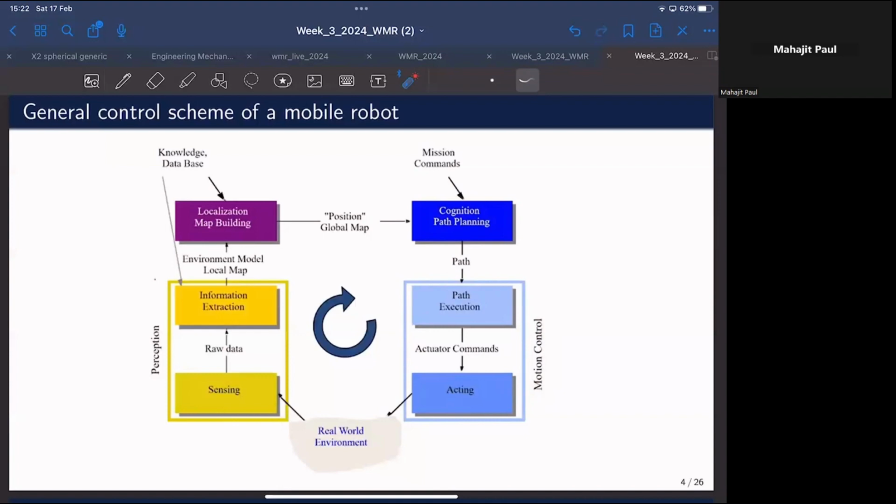By comparing all the data internally from the robot as well as what it is receiving externally, it will make sure that the robot stays on the path that was already selected during the path planning process. So the controller makes sure that the robot stays on the path without veering too much from the desired path, and it also gives the commands to the actuators.